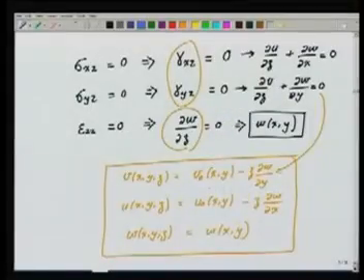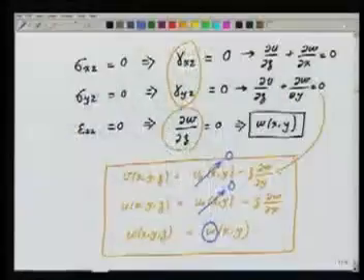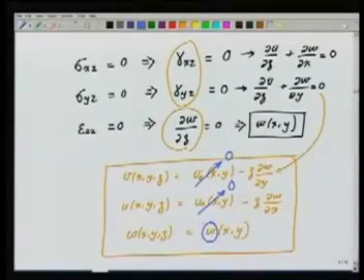It can be further shown that in this case, for the isotropic plate, the functions u0 and v0 will be 0 everywhere, because they will be governed by the planar elasticity problem. Because this is a bending dominated problem, the only displacement you are going to have is w, and due to w, the u's and the v's will come.